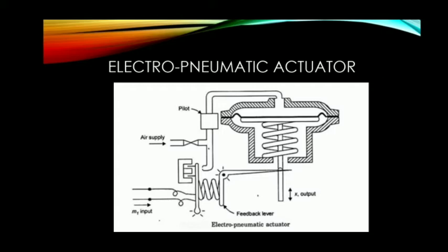In electro-pneumatics, the signal medium is the electrical signal; either an AC or DC source is used. The working medium is compressed air. Operating voltages from around 12 V to 220 V are often used. The final control valve is activated by solenoid actuation. The resetting of the valve is either by spring, single solenoid, or by using another solenoid, a double solenoid valve.